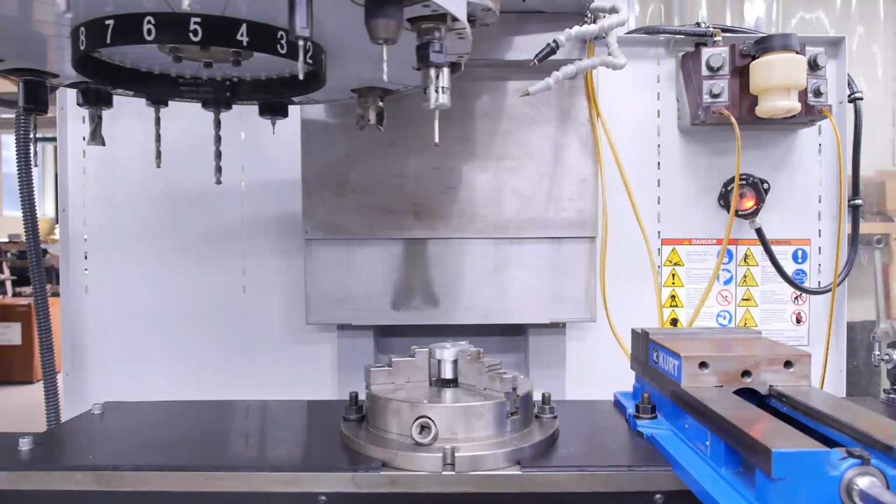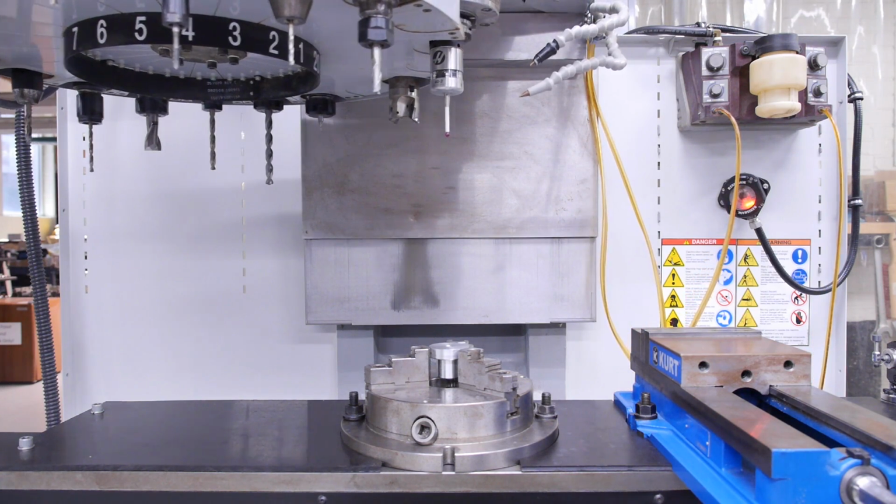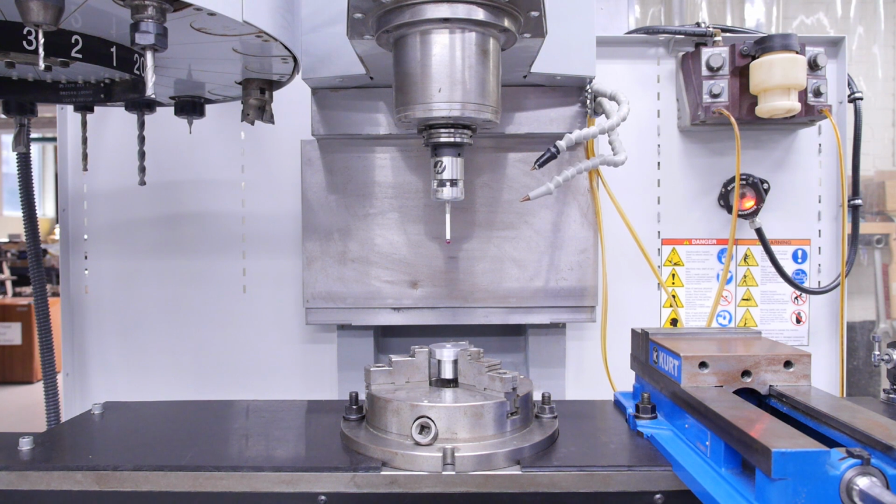After pressing the cycle start button, the machine immediately performs a tool change and rapids the tool probe to 5 inches above the workpiece. The program comment accompanying the M00 program stop at this location instructs the operator to turn the rapid override down to 5% to 25%, whatever he or she is comfortable with at this point running the machine.